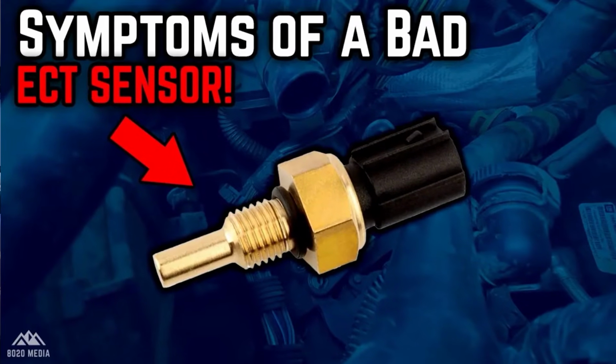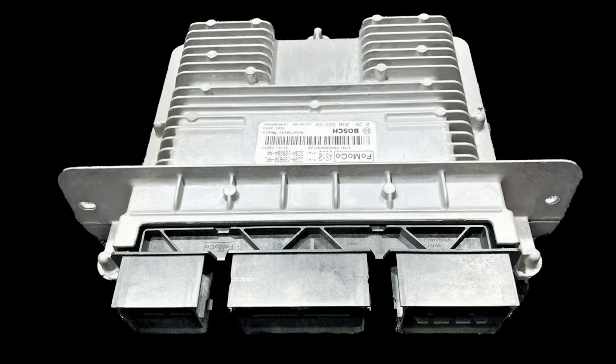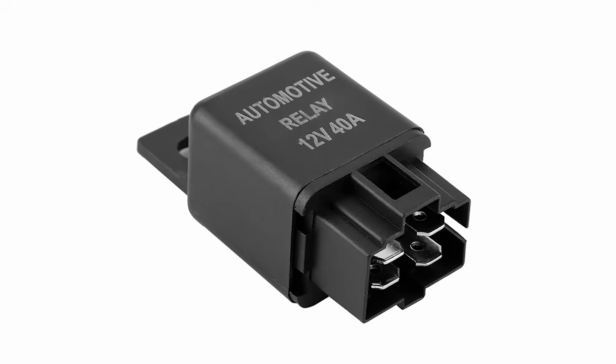These codes are critical for pointing you in the right direction to start diagnosing the issue, since a lot of the times, depending on what the fault code is and what the issue is, you can also receive other fault codes that can help point you in the right direction. For example, with P0480, if you're also receiving some fault codes indicating a potential issue with the coolant temperature sensor, that could point you in the direction of that sensor potentially being the issue. Or if you're getting all sorts of various fault codes, that could potentially point to an issue with the PCM itself.